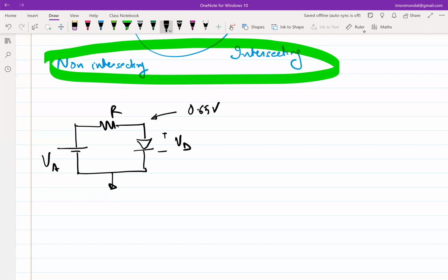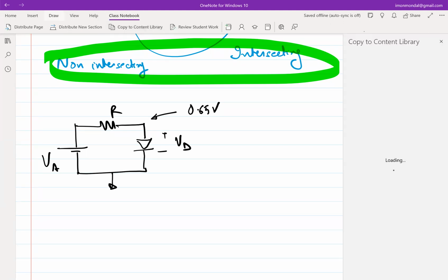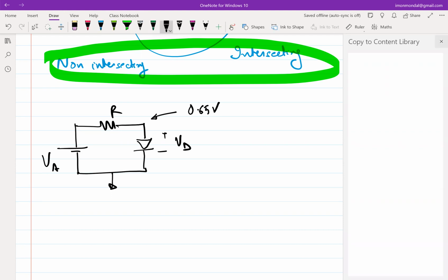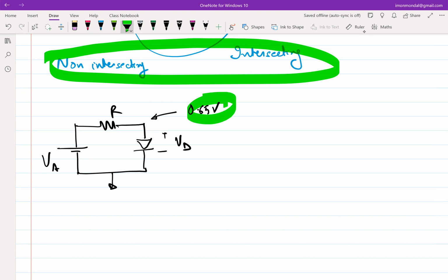Yeah, so the question essentially is that whenever I have been doing this diode analysis, I started off, even in the question paper, and said that for finding quiescent point, assume this to be 0.65 volt, regardless of the current. If it's on, assume diode to be 0.65 volt forward bias. So is this sacrosanct for 0.65, or is it something we do just to make life easy?